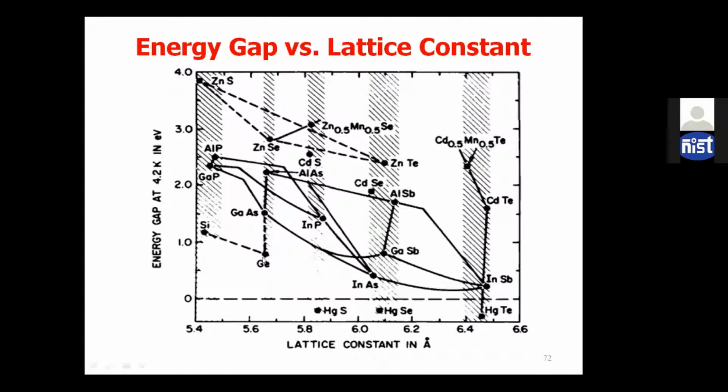Yesterday I already told you, from 2000 onwards, in CMOS technology, strain technology has had a very emerging impact on the semiconductor industry. You see germanium and silicon lattice constants. If you make a compound semiconductor by taking silicon and germanium, and grow that silicon germanium over germanium, then it is a totally lattice mismatch. So it will give you strain.